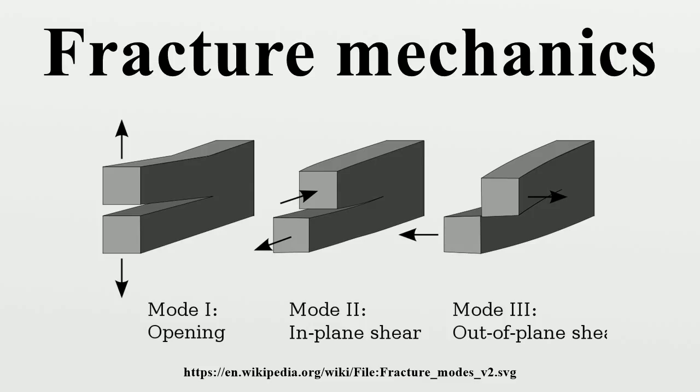An explanation of this relation in terms of linear elasticity theory is problematic. Linear elasticity theory predicts that stress at the tip of a sharp flaw in a linear elastic material is infinite. To avoid that problem, Griffith developed a thermodynamic approach to explain the relation that he observed. The growth of a crack requires the creation of two new surfaces and hence an increase in the surface energy.